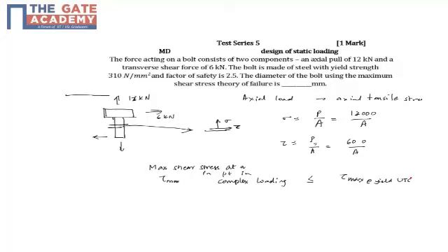That's what it predicts. So the maximum shear stress from the complex loading is what we need to find out from the given problem. It should be less than or equal to the shear stress at the time of yielding, for failure not to happen. But then we provide a factor of safety, so tau max at the time of yield by FOS.